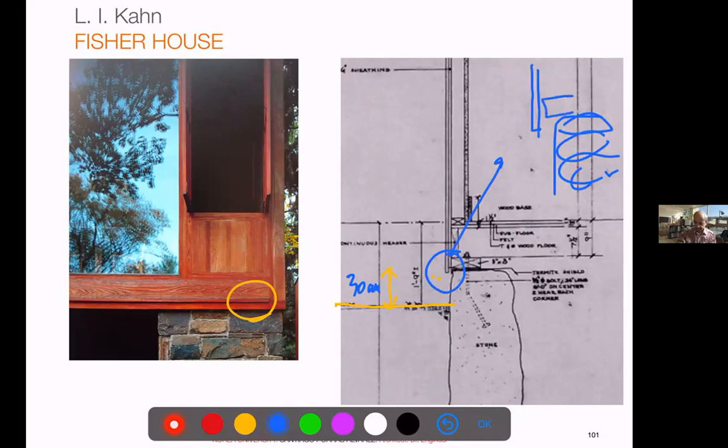which is slightly away from that wall and has a small little lip. This allows the water to slide and to drip, right? So I call it a dripper or drip, right? So the water does not go to the joints, which is the critical point, right? This is an important thing. Then you have another element, which is the waterproof element between stone and timber.